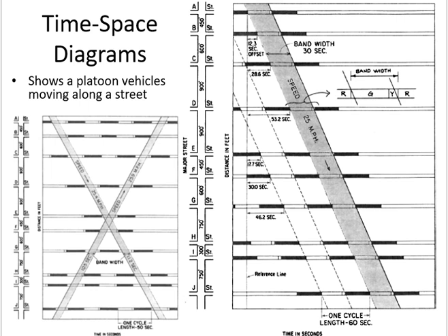Then now you start doing the coordination. What is the purpose of coordination again? To prevent queues, for continuous flow, right? So I want the driver who starts from here, when he reaches the other intersection, the signal should be what for him? Green. So I need to time the start of green for the next intersection with reference to the first one.